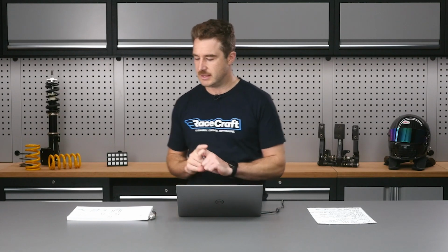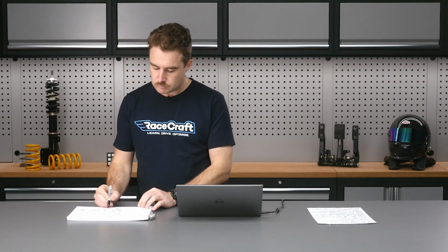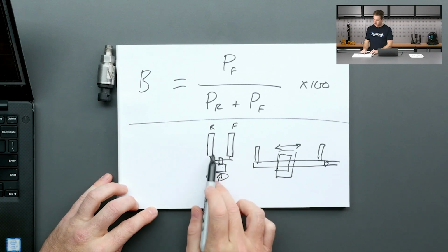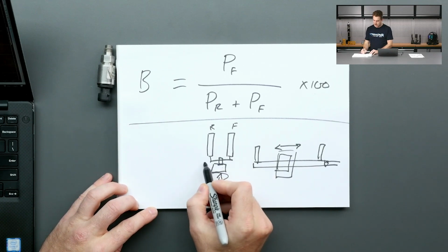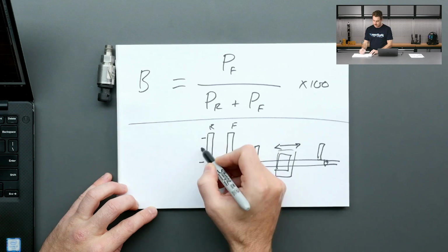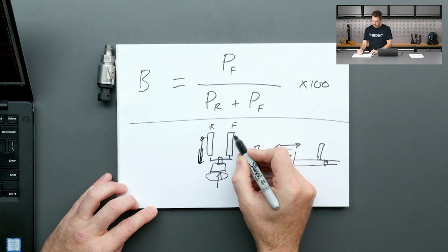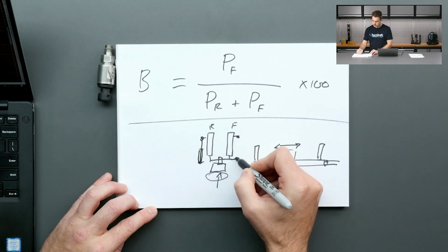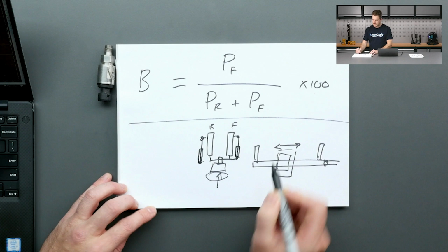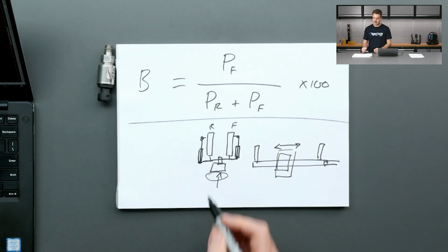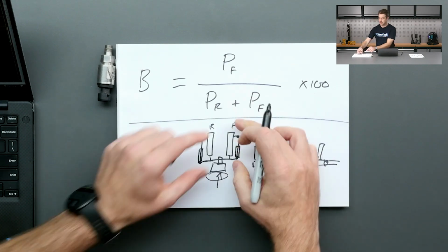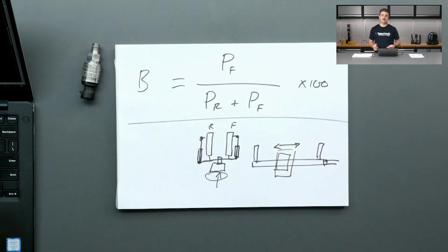With that position, along with the pressure data, we can start to do some quite useful and interesting stuff as far as diagnosing problems with our braking system. If we come across to the overhead again, back to our setup where we've got these two different master cylinders, the way it works is usually just having a little linear potentiometer on each master cylinder. The idea here is that not only are we measuring the hydraulic pressure in the hoses, we're also measuring how far each one of these master cylinders is actually moving.